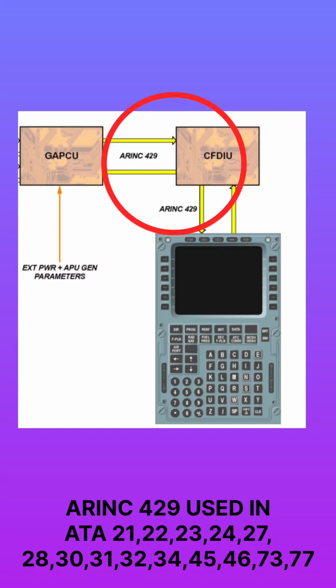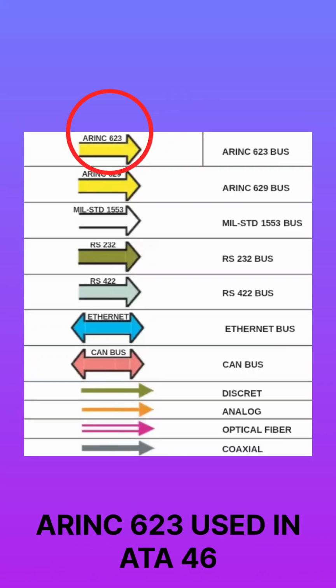This bus is an industry standard used on all commercial aircraft. It is the specification that defines a local area network for transfer of digital data between avionics system elements, and it describes how an avionics system transmits information over a single twisted and shielded pair of wire to all other system elements that need that information, up to as many as 20 receivers.